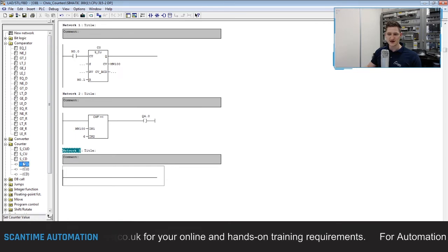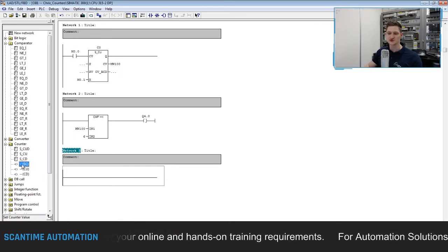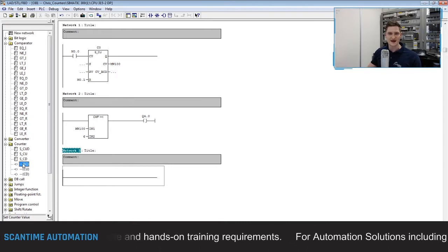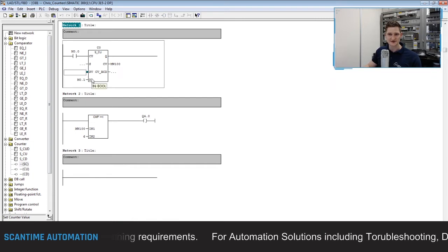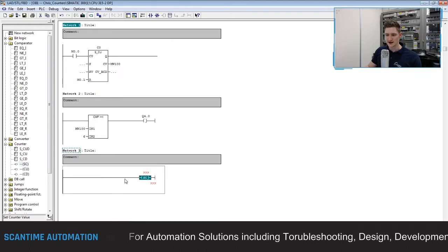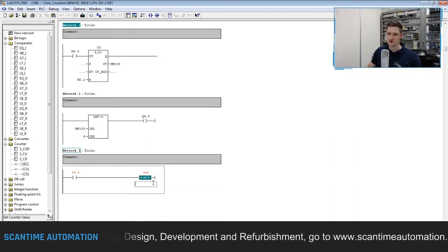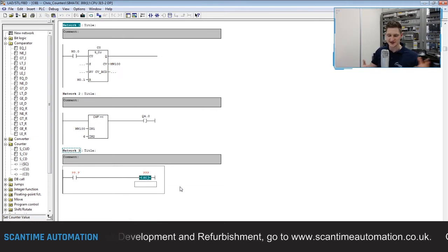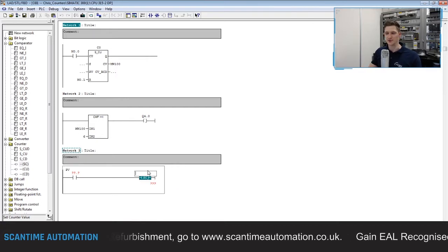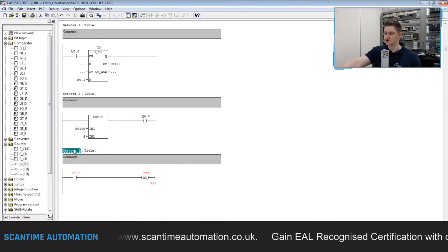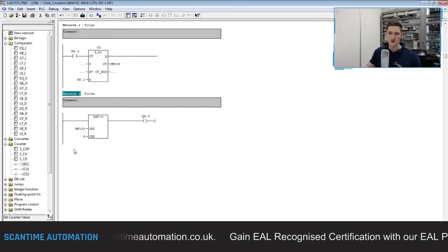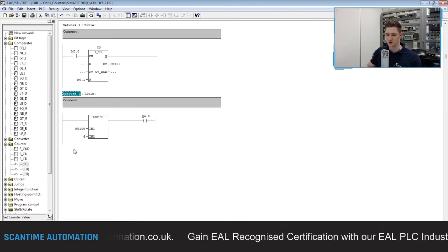Now you'll notice here the first thing inside of our S7 counter instructions is SC. That there is our set count instruction. If you remember the S and the PV inside of this S5 counter, that is effectively what that is. If we move that into our network and assign a contact to that, when this contact turns on, it's going to move whatever value is in here, let's just say 6 like it was before, into our counter. Now, because we already said we don't need this, we're going to delete that network from the program. We only need that if we're going to use the countdown counters, which we're not.